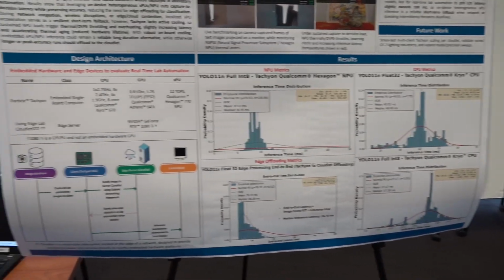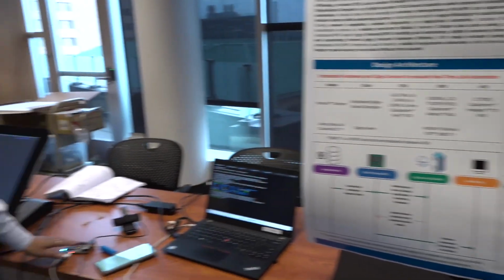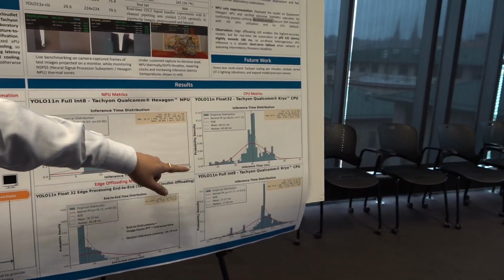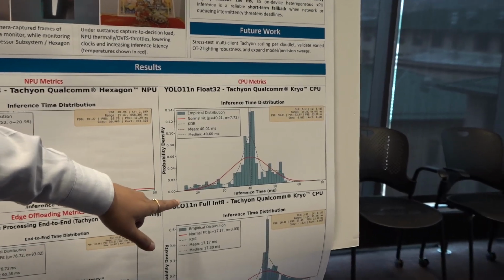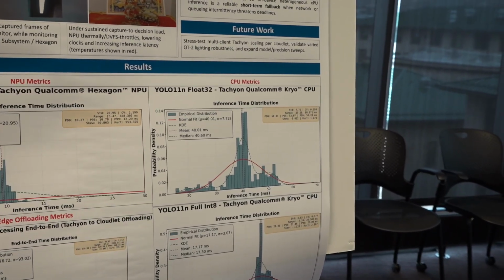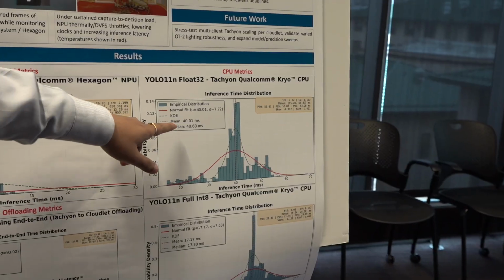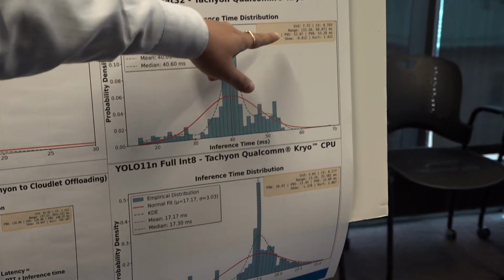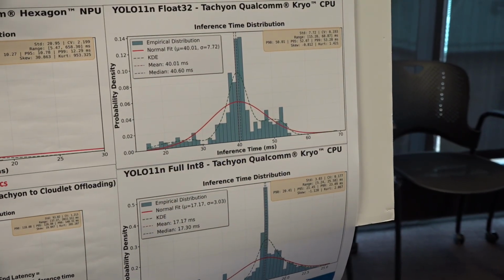We also tried to use the onboard CPU on this device to run inference with full-blown float32 and a fully quantized int8. We got inference latencies of 40.01 and 17.17 milliseconds, with the P95 well below the 100 millisecond range.